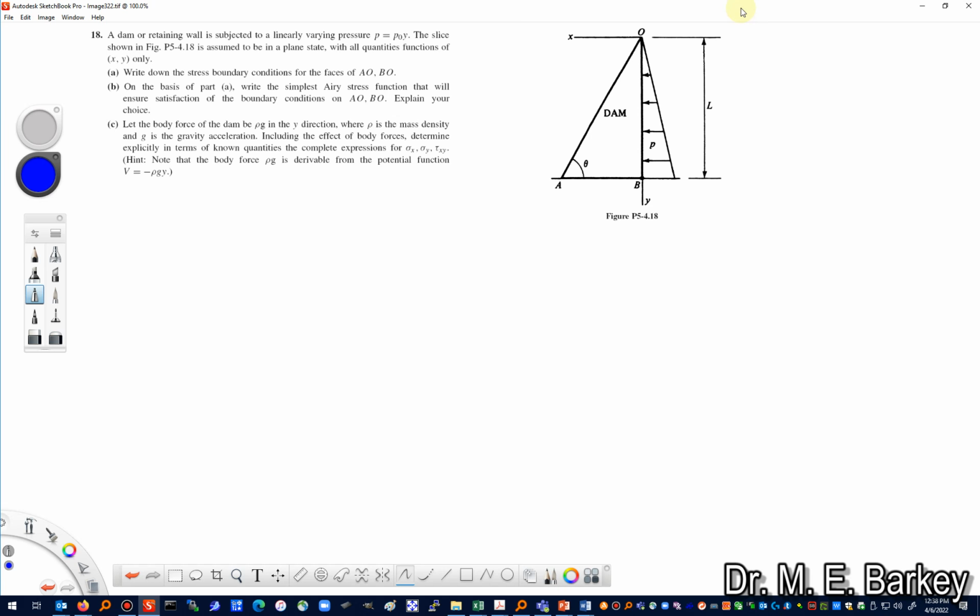And so if we look at that first, then there are a couple of reactions that we'll get on the bottom surface of this dam. Now this goes from A to B. This isn't what the question is asking for, but this is something I do want you to know. There will be a force that goes horizontally to resist the resultant force from this distribution. There will also be a bending moment that acts on the bottom surface of this dam that would tend to go over that way. Well, how do we find the value here?